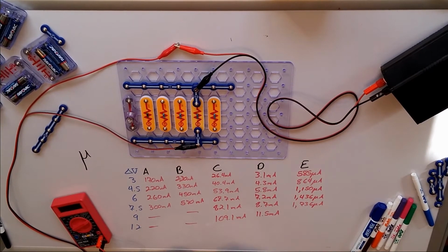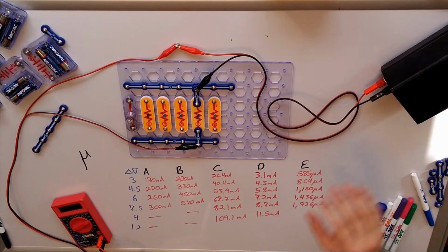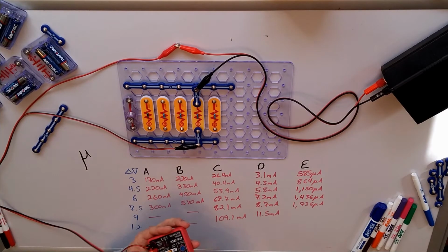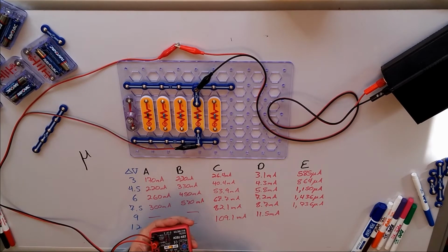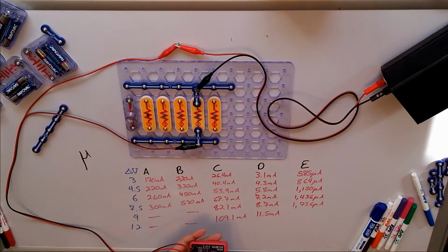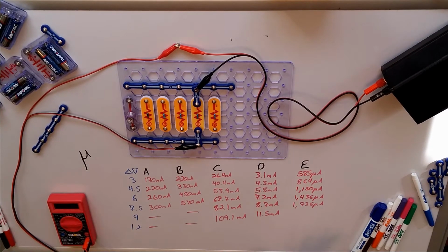1,736 microamp. Okay. Let's go up to 12 volts. I'm going to go ahead and show you this because we've got it. On my meter, it just says 1 with nothing after it. Whenever you see that, it means that we're on too low of a setting and it can't accurately measure it. So we need to go to the next setting up. Now it goes from a 1 instead to an actual number. So whenever you see that 1 with nothing else with it, it means you've maxed out your sensor and we've got to adjust it to something different.